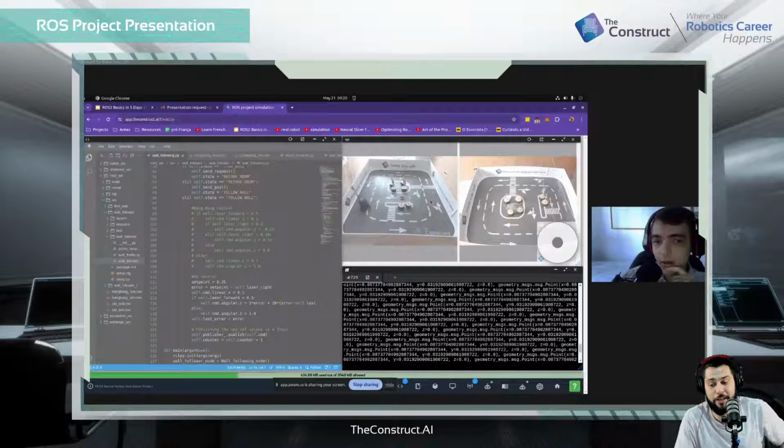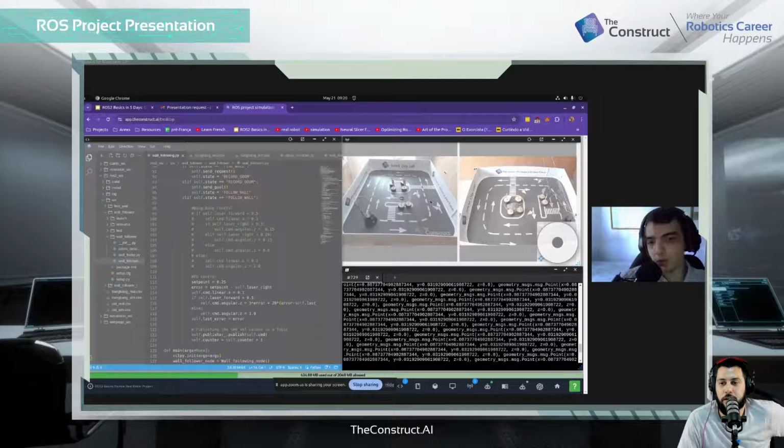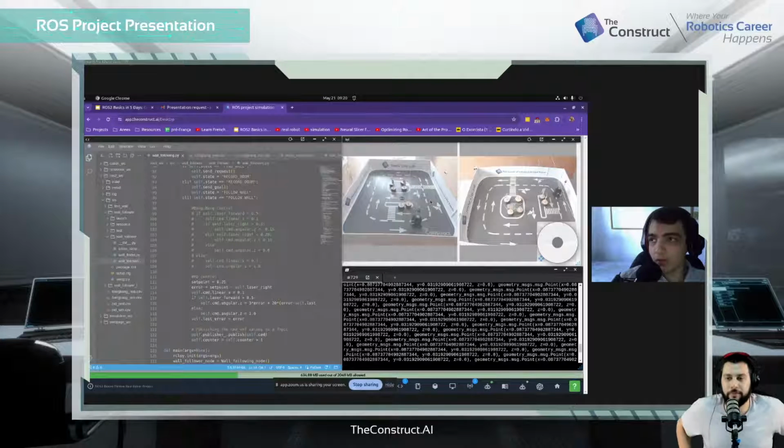Okay, that might be another issue. That's an issue because when the robot moves, the angle moves, so the value changes a lot, right? Yes, and that's part of the non-linearity of the system. We can linearize it around a very small angle, the z angle of the robot.